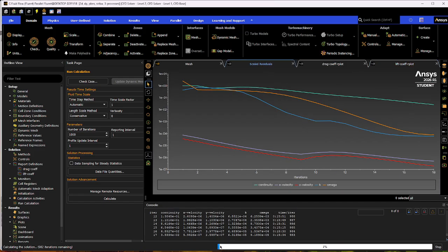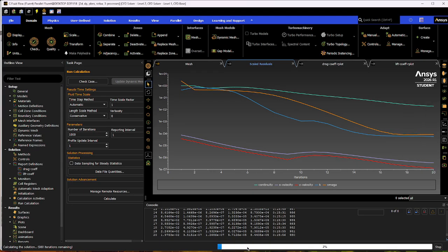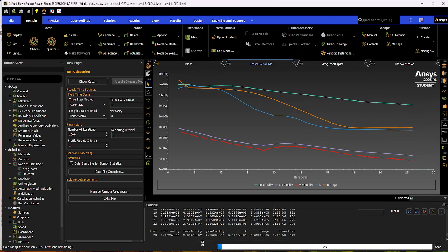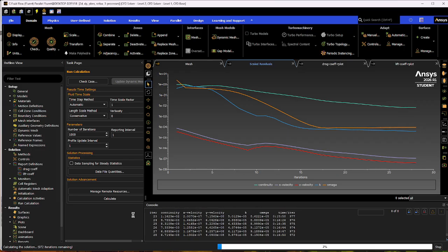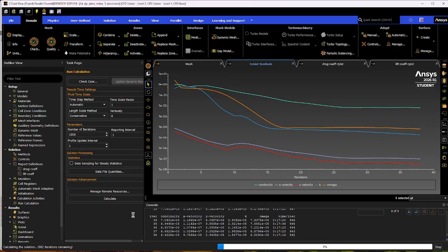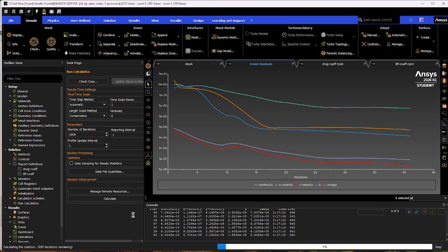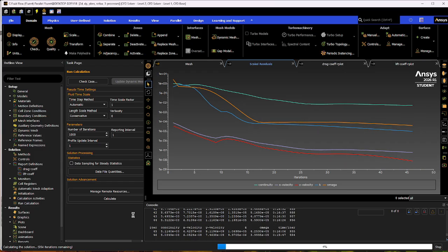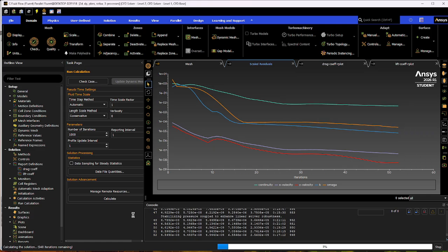So usually it converged pretty early, so like anywhere between like 30 and 40% of the iterations for the low angles of attack. It would say, oh, at a certain iteration, convergence was reached. So it's not going to need that many iterations for the low angles of attack, but for the high angles of attack, like I said before, for 21 degrees, it takes longer, way longer.